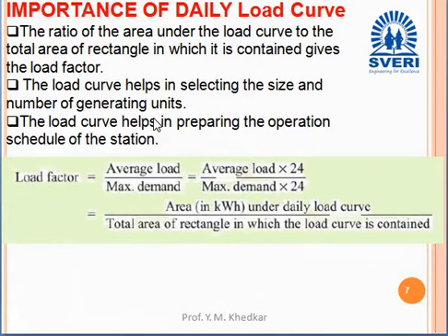So the load curve is also helping the consultant to decide the size and number of generating units. According to the load demand, we are designing the size and the number of generating units in the power plant. The load curve helps in preparing the operation schedule of the station. Means how many generating units we will have to start, that particular part will be decided by taking a look at the load curves.